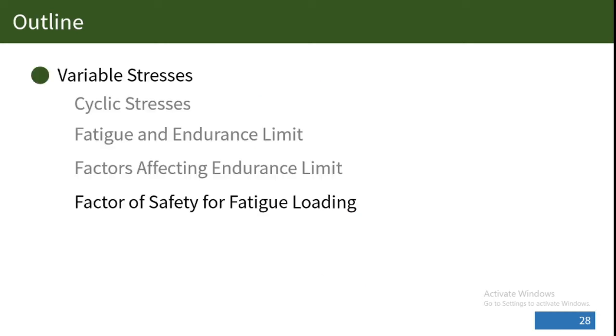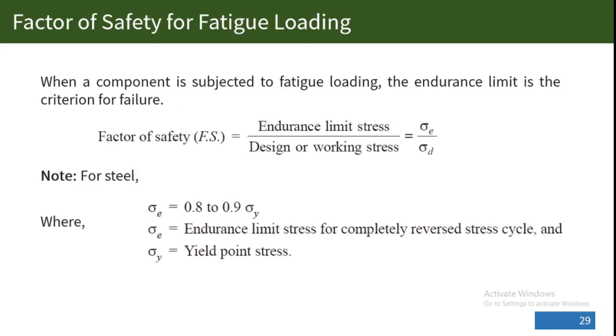Now, let us proceed with the factor of safety for fatigue loading. When a component is subjected to fatigue loading, the endurance limit is the criterion for failure. Alright? So for instance, fatigue denotes the failure of a material. Thus, the endurance limit will be used as a criterion for failure.